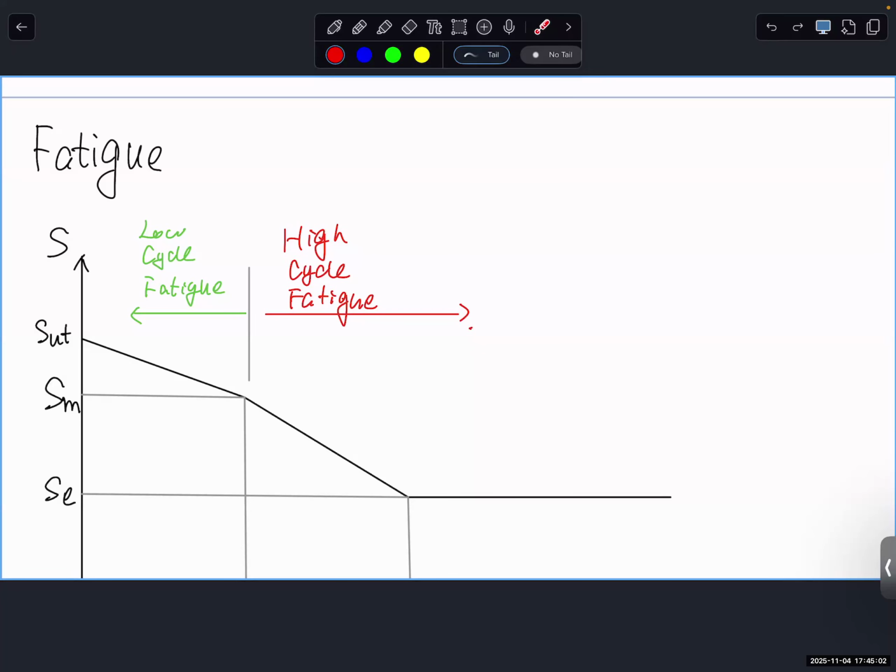So it's more like tensile back to zero, tensile back to zero, repeatedly. The maximum tensile stress at that location doesn't really damage any structure or cause pain on your bone. But if you keep opening and closing, consider how many times you do it every day and the accumulated damage. That is considered a fatigue problem.